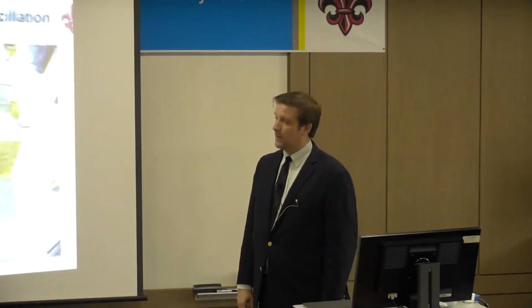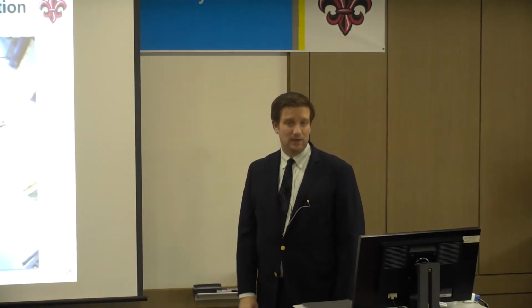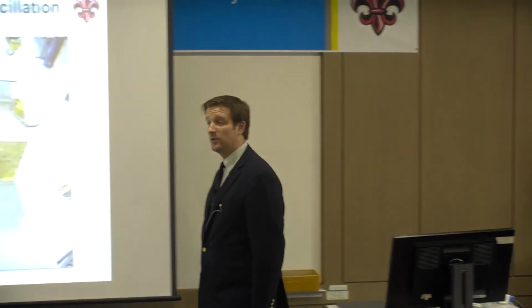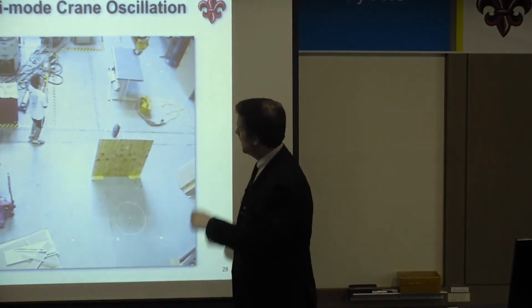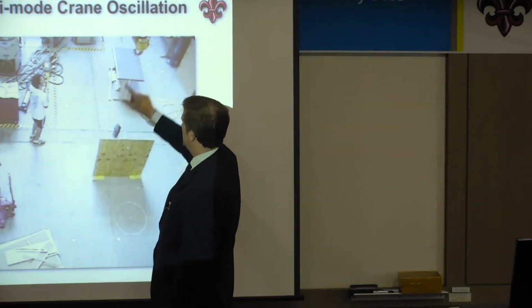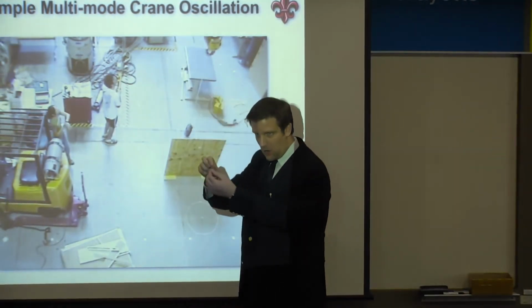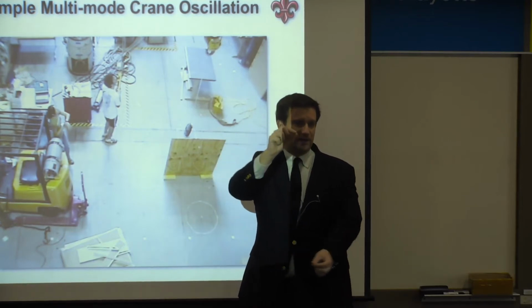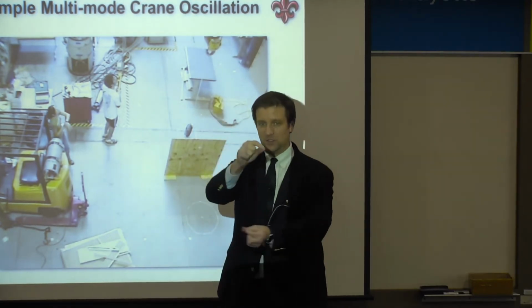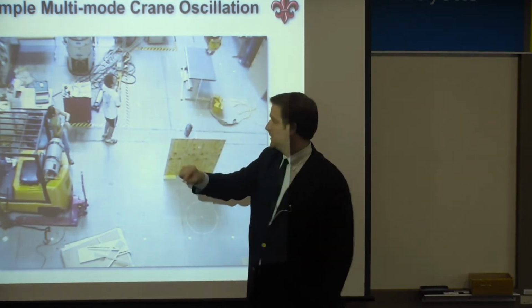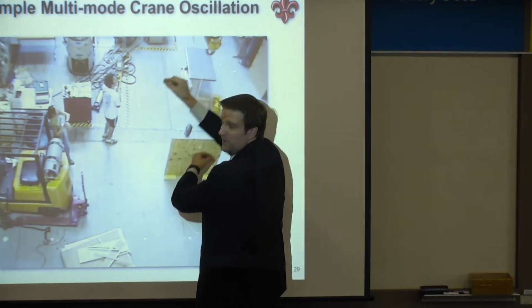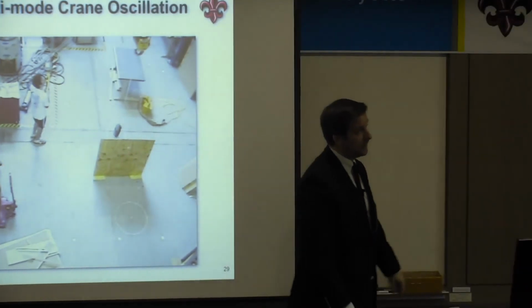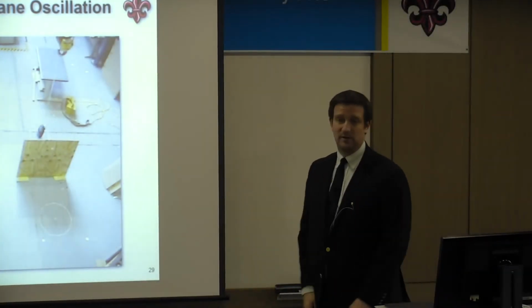What's cool about this input shaping, so far we've only talked about one frequency, is that it's quite easy to do for multiple frequencies as well. So here's another crane at Georgia Tech, the same crane you saw before actually, but a different kind of payload. This long, skinny payload gives you not just pendulum motion, but string-type vibration. So you'll see in some cases that the weight and the hook will be moving in opposite directions. And really expert crane operators still have trouble with this one.